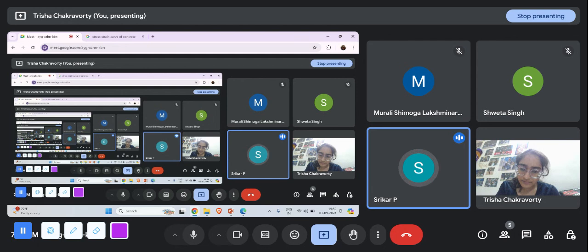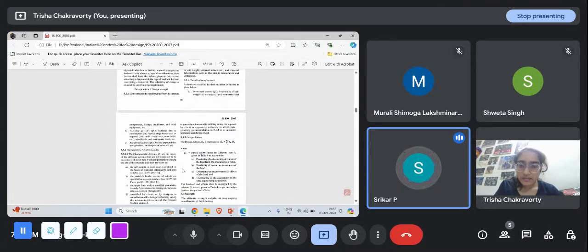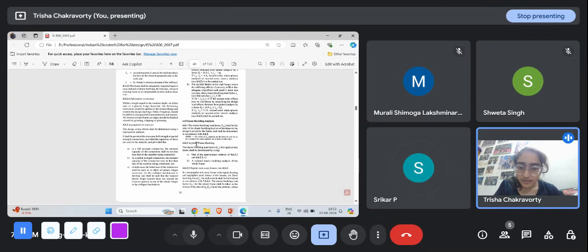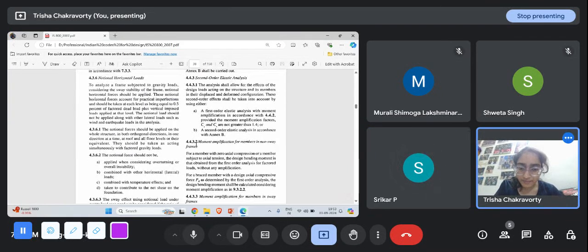Yes, but in those last situations there are two to three formulas. In one case we are going through what you said. In another case we have the resultant, and that resultant is compared to the factored load. In the other case we have the square root of sigma square plus three tau square. So there are two to three different combinations. When should each be applied? Which one should be used when?